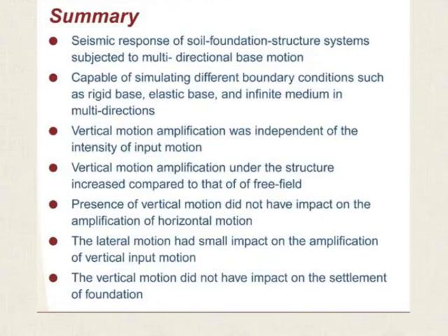So, in summary, the seismic response of soil foundation structural systems subject to multi-directional base motion was modeled using this DEM technique. The technique is capable of simulating different boundary conditions such as rigid base, elastic base, and infinite medium in multi-directions. The vertical motion amplification was independent of the intensity of input motion. The vertical motion amplification under the structure increased compared to that of the free field.